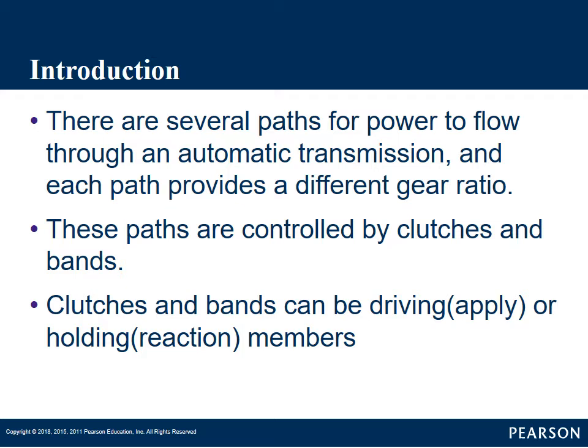So one member, the input, is your drive or your apply, and that is the power source coming from the engine into the transmission, goes through a clutch pack. Essentially, we apply a clutch pack or a band which drives one of the members of our planetary gear sets. Then we use a clutch pack or band to hold another member, and then our third member of the planetary gear set is our output.